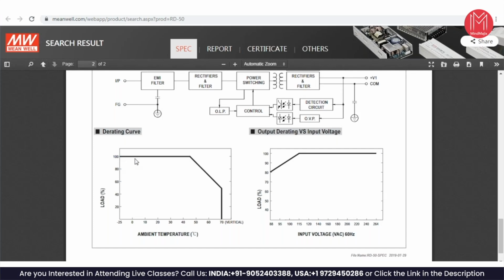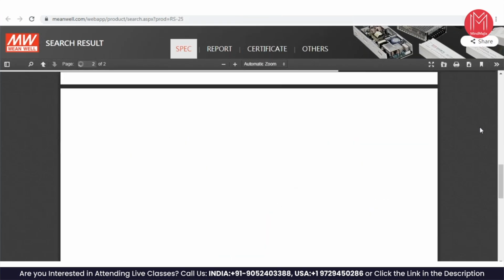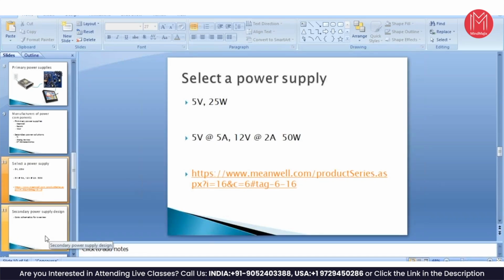This one right here is the derating curve. It basically supplies 100% until 4.5 amps. Until 5 amps it should have been, so somehow it's shown, maybe not very accurate. Until 6 amps maybe. After 7 amps it falls down. On overload, it cuts off, for anything over 7 amps. So here, let's look at the 5 amps. That's how we select power supplies from that.